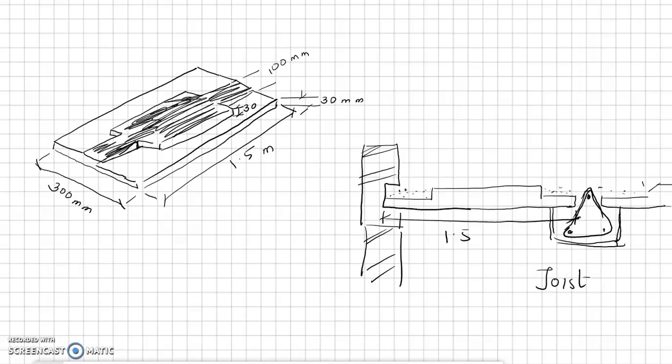At 1.5 meter you are placing a joist. What is the distance at which you have placed the beam in your classroom? Somewhere around 3.5 meters. So at every 1.5 you are placing a joist. Okay. And then since this all lower part is there, here there will be additional steel provided. There are steel rods provided here, which you will see like this in the cross section.